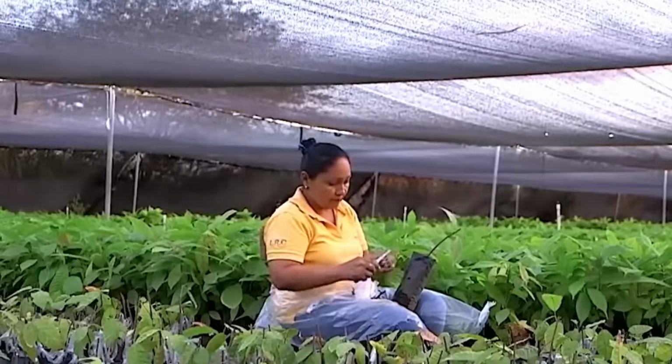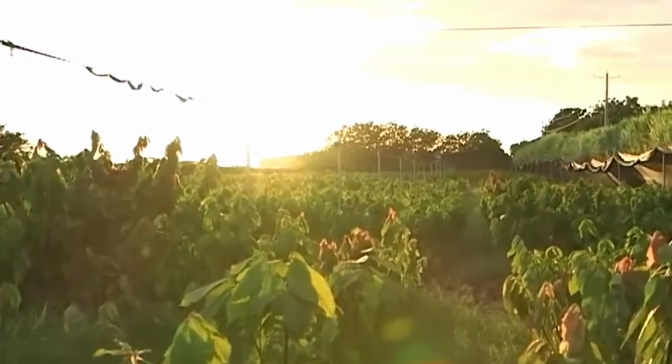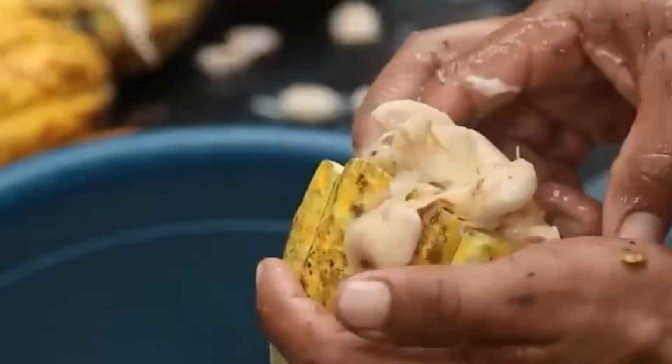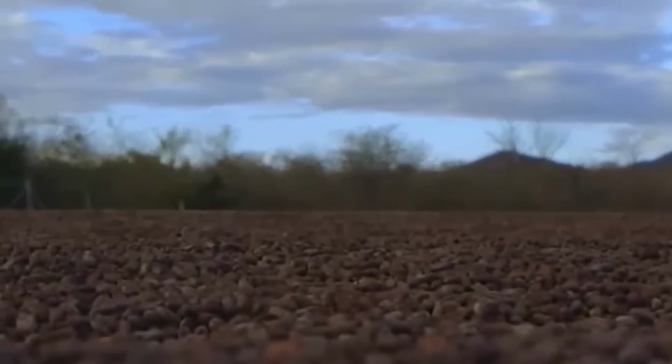Accepted packages are collated into larger trays or cartons using pick-and-place robotic arms equipped with vacuum grippers. Cartons are assembled, filled, and sealed using hot melt adhesive and barcode labels applied on the side panel. Shipping cartons are scanned and aggregated onto pallets using automatic palletizers that form specific stacking patterns for warehouse efficiency.